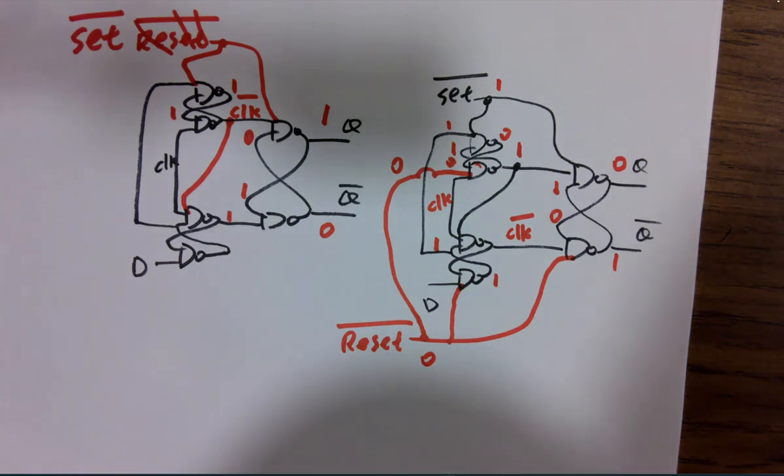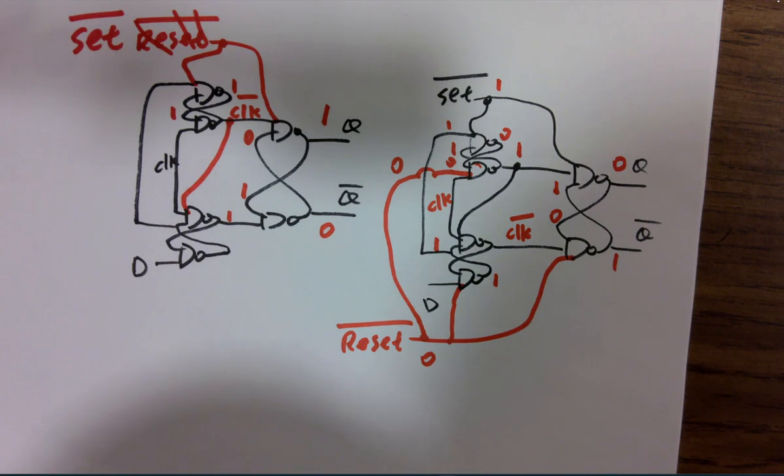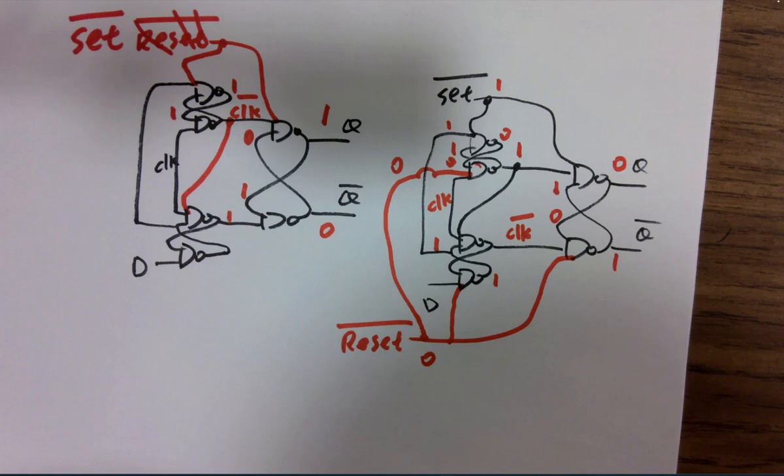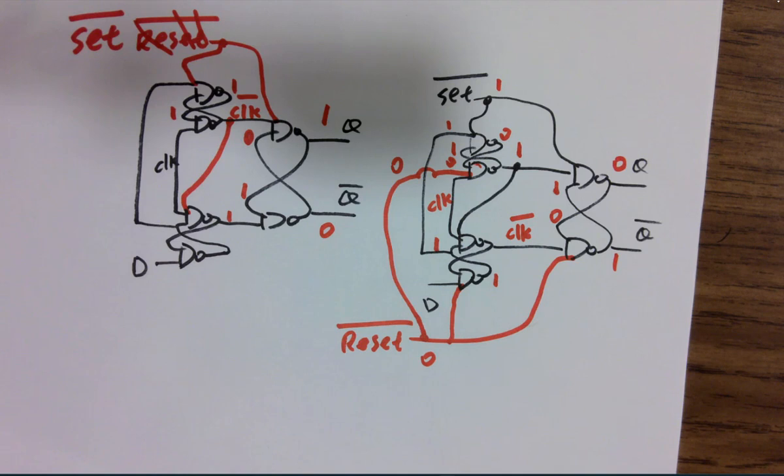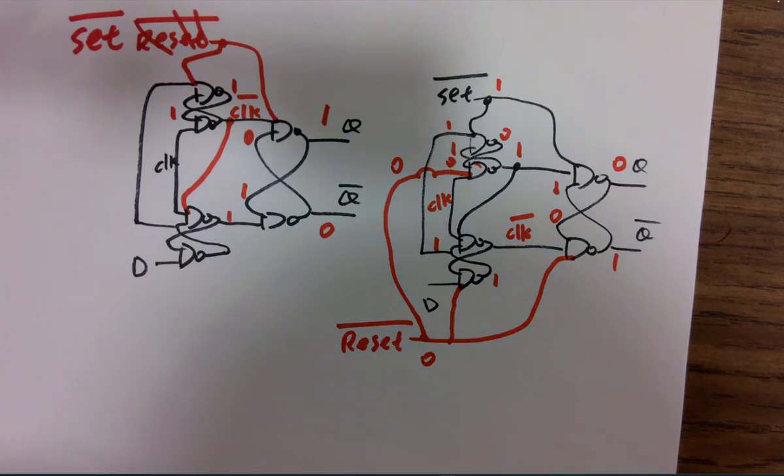So now we know that it's a pretty good circuit design, very smart, and it's a D flip-flop, rising edge trigger, set and reset, perfect. You can see this structure is being used in a lot of ADC designs, the D flip-flop, or a lot of other digital circuit designs. It's a very important schematic to learn. So that's why we have this in this class. It's not in the textbook, but it's important to know.